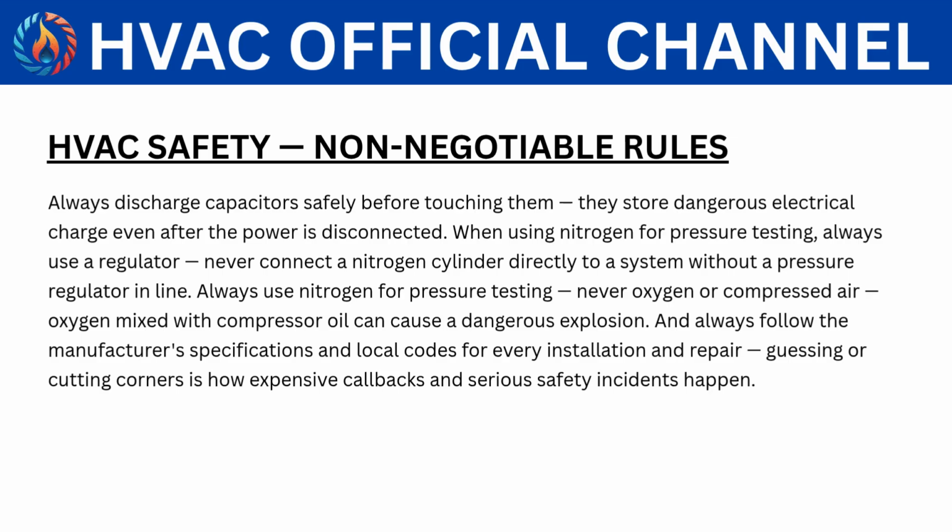Always use nitrogen for pressure testing. Never oxygen or compressed air. Oxygen mixed with compressor oil can cause a dangerous explosion. And always follow the manufacturer's specifications and local codes for every installation and repair. Guessing or cutting corners is how expensive callbacks and serious safety incidents happen.